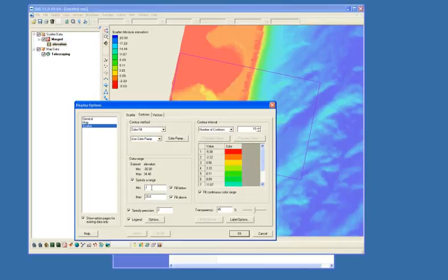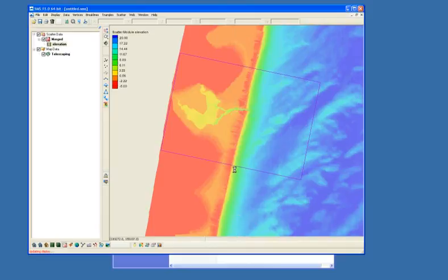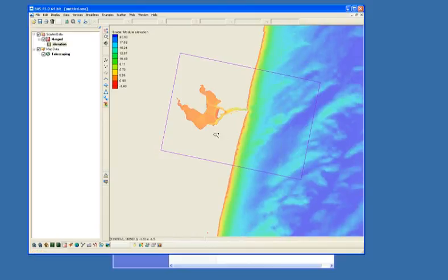I normally just choose something between -1 and -2. I think for this particular case I chose -1.4, and I am choosing not to fill below this value. So anything which is higher on land than 1.4 meters above the water, I'm choosing not to fill below it. And then when I click OK, we should see a vastly different grid.